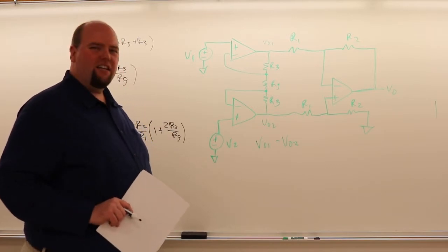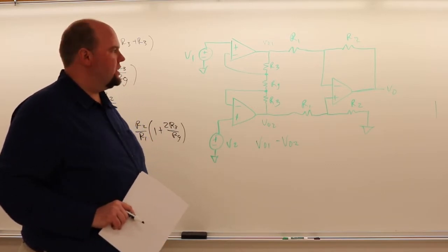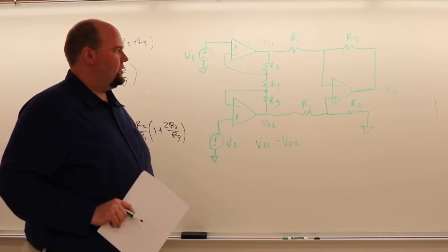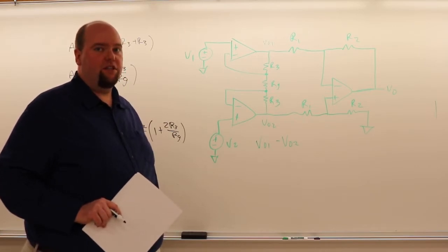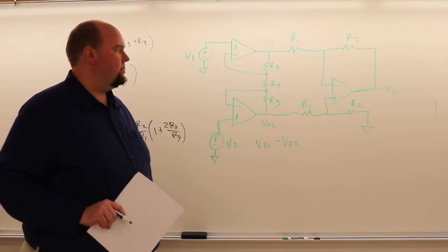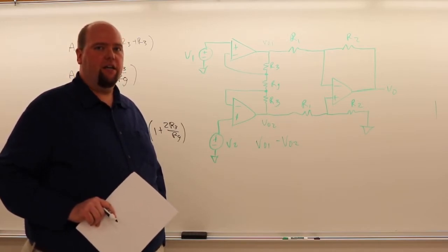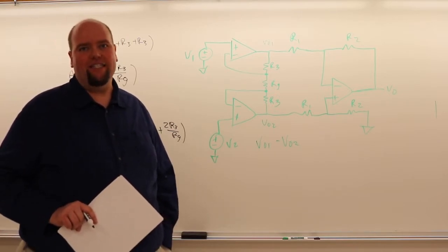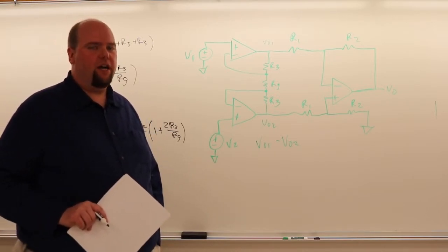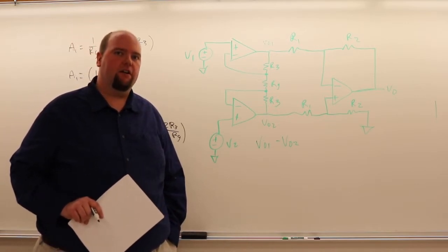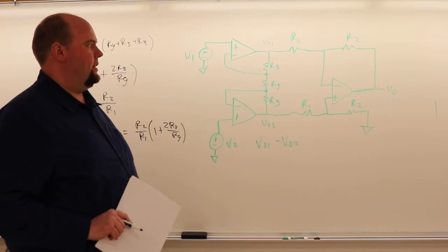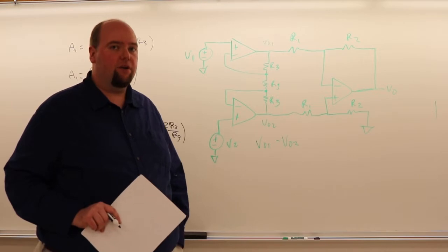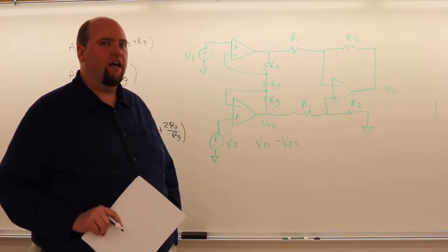You have to be a little careful though with potentiometers, because potentiometers used as resistances in feedback circuits like this are, as you know, very sensitive to these values of resistances. Sometimes potentiometers are a little bit noisy. Sometimes you will get acoustic noise, vibration noise in potentiometers, just due to the fact that you have a resistance set by a mechanical connection. You don't actually have a chemical bond between the materials, you have a mechanical contact. And in lower quality potentiometers, that can vary. Also, the materials potentiometers are made out of are often not quite as linear with temperature as other materials.